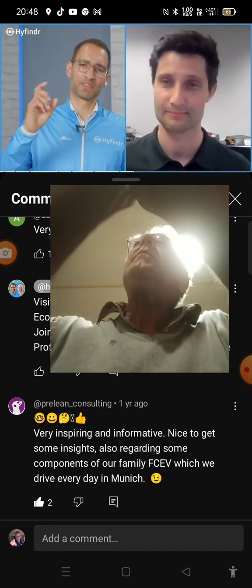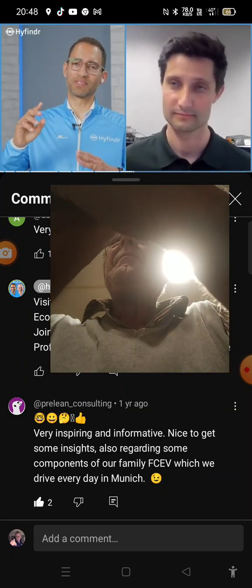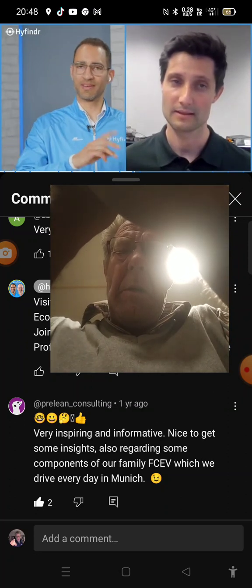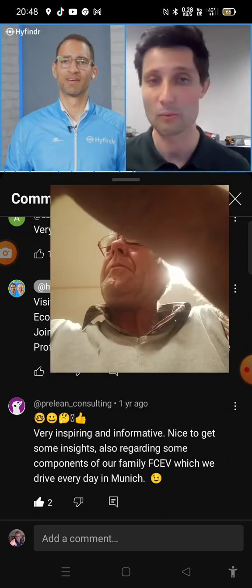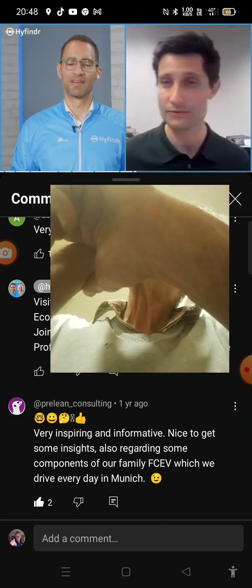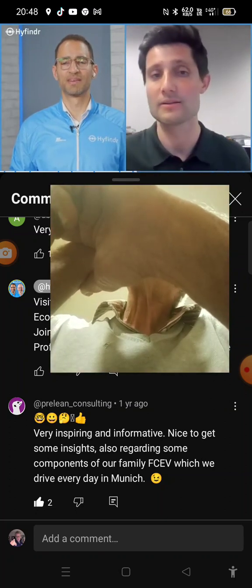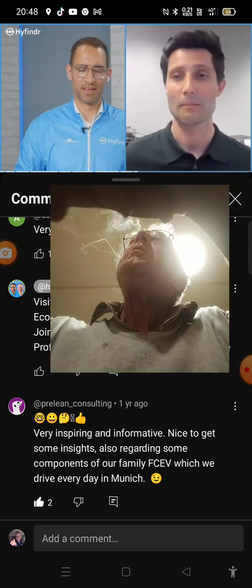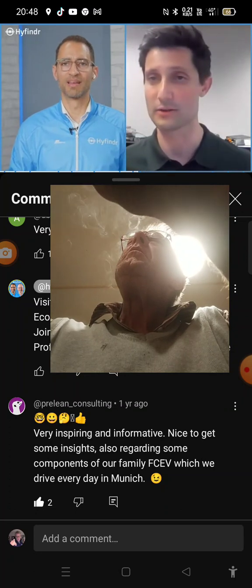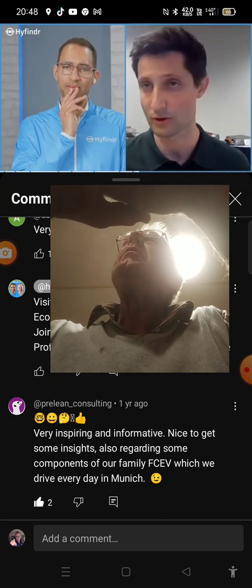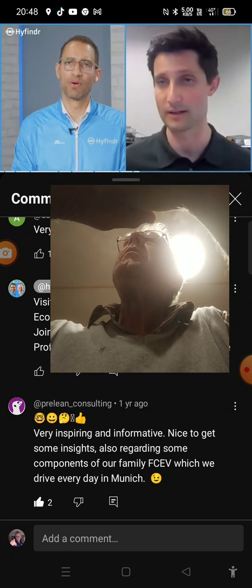And I see there was cooling. I saw from the diagram. So what is actually being cooled is the electric motor. That's what's being cooled. So obviously within that system, we have a couple of sources for losses. Yes. One is, for instance, the gas bearings that generate losses. Yes. But mainly it is the electric motor, as you indicate. Yes. And we can either cool it with water or with a cooling medium, or it is air cooled.